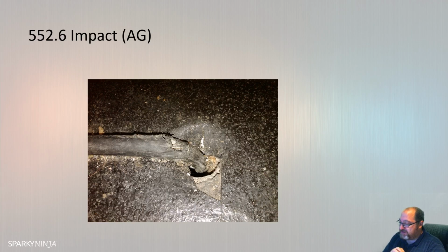The degree of protection of the equipment shall be maintained after installation of the cables and conductors. A cable installed under a floor or above a ceiling shall be run in such a position that it is not liable to be damaged by contact with the floor or ceiling or their fixings.